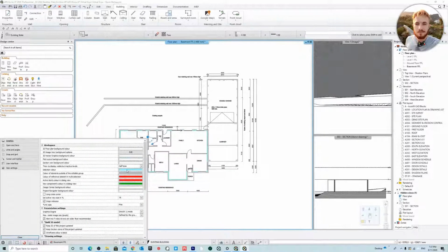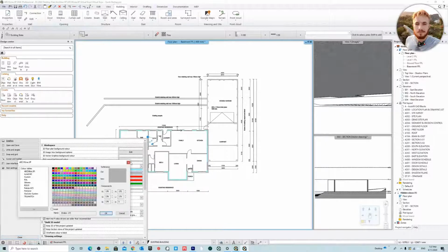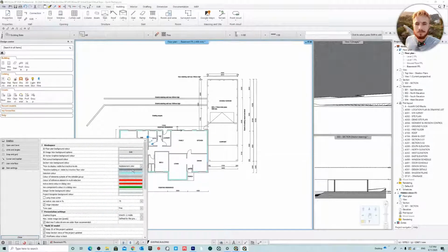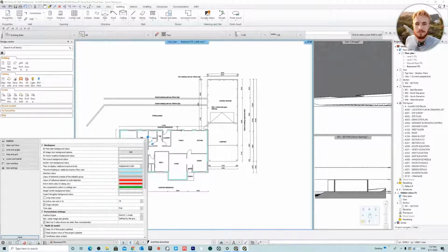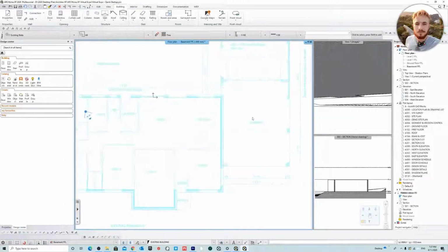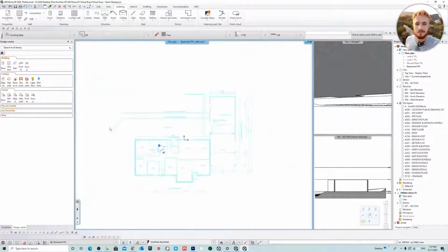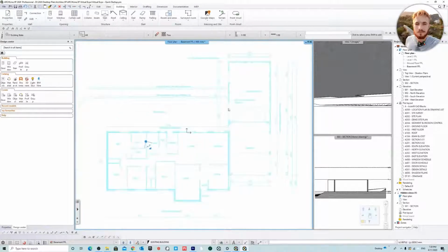You can do, let's see, if we do this as color, replacement color, inactive but building. Okay, so this one, we can select this to custom. Let's say like a light blue color like that, just so it's slightly faded. Okay, now you can see your trace layer. Sorry, your trace level, your ghost layer.